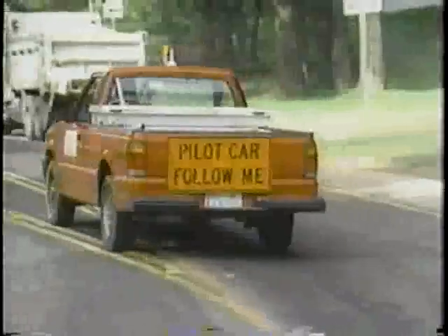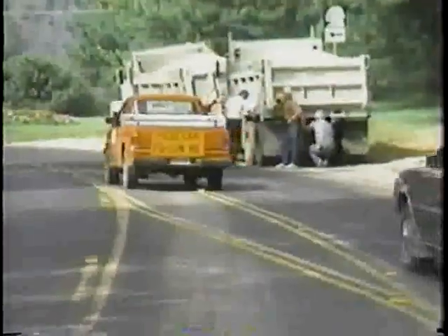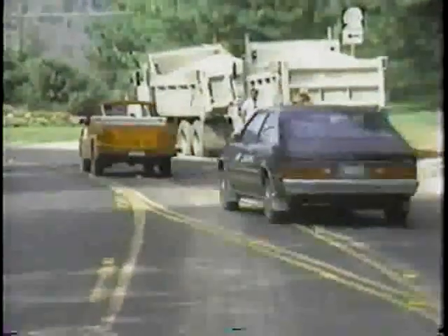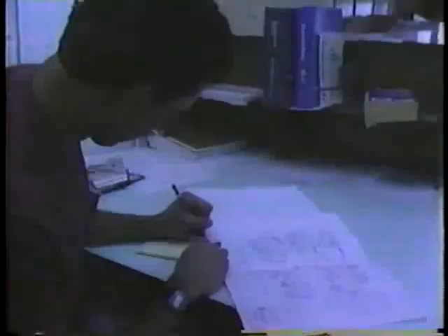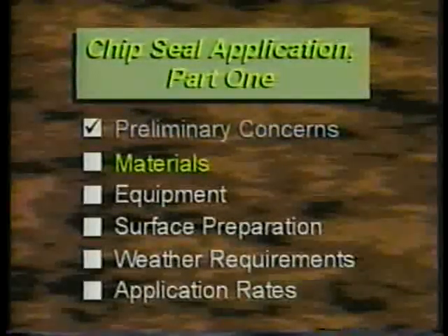To further protect motorists and the new chip seal, pilot cars may be needed on projects constructed under traffic. So carefully review the traffic control plan. Make sure it's approved and see that it's followed throughout construction. The next step is to check the materials.